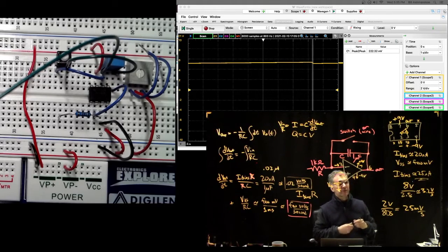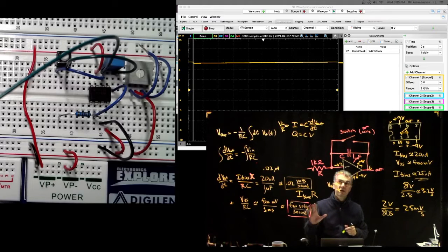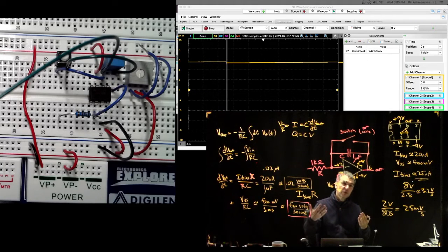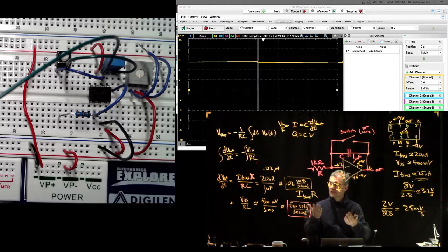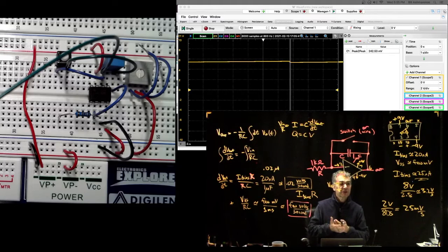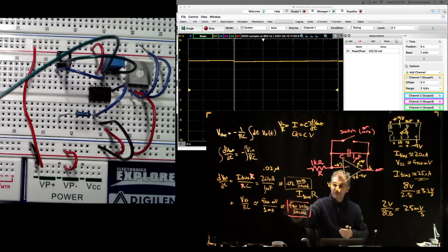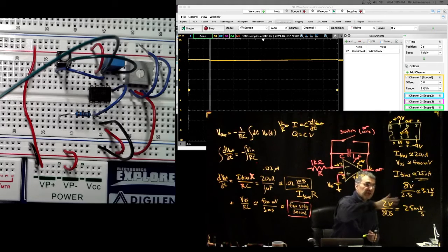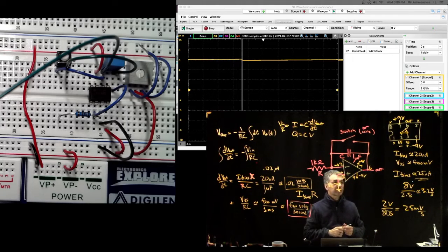So we effectively measured the slope the first time. It was some combination of V offset and Ibias causing that initial slope. We didn't know a priori which was which, but based on orders of magnitude, we thought it was probably dominated by V offset. So, assuming that it was dominated by V offset just for the moment, then we inferred a value of V offset of a few millivolts, but we don't really know that yet.